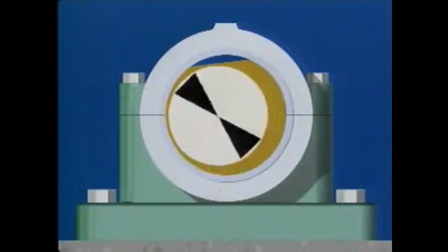While the shaft's at rest, the weight of the shaft squeezes most of the oil out from between the shaft and the bearing. This places the bearing and the shaft in metal-to-metal contact. But when the equipment is started, the shaft begins to roll slowly, and the motion drags oil underneath the shaft. Oil sticks to the shaft as the shaft turns, and the oil is carried between the two surfaces.